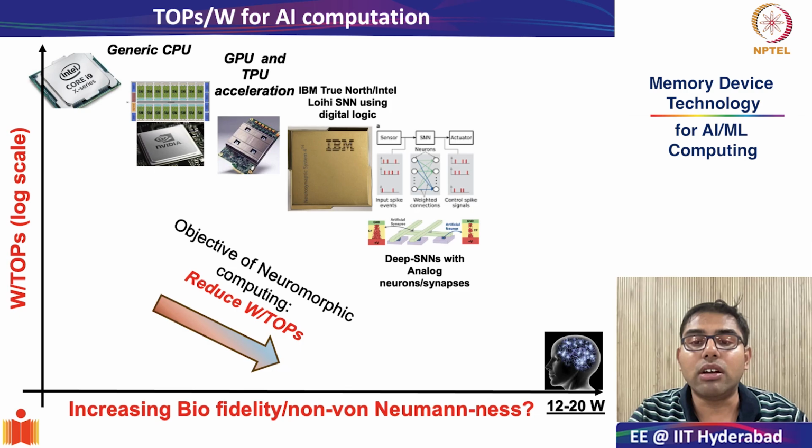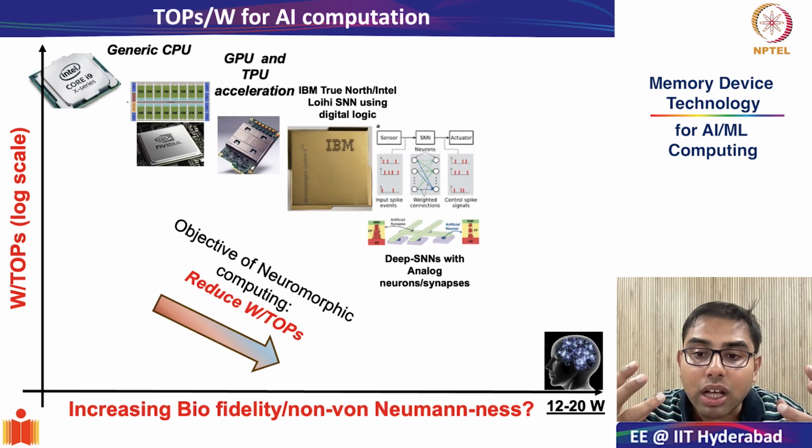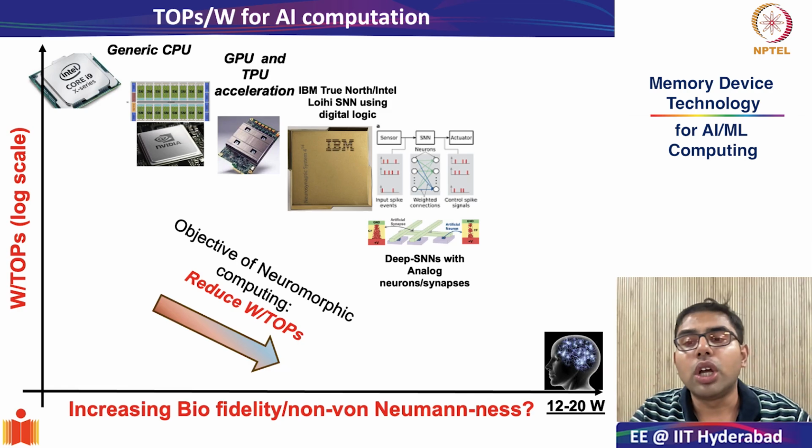Also, we discussed some key challenges preventing a full-scale analog implementation of large-scale SNNs for really complex tasks. They were primarily device mismatch and noise, which had limited precision, and therefore you had the difficulty of making these adaptive learning rules purely analog and implementing spiking neural networks only for simple pattern recognition or low dimensional sensory tasks.